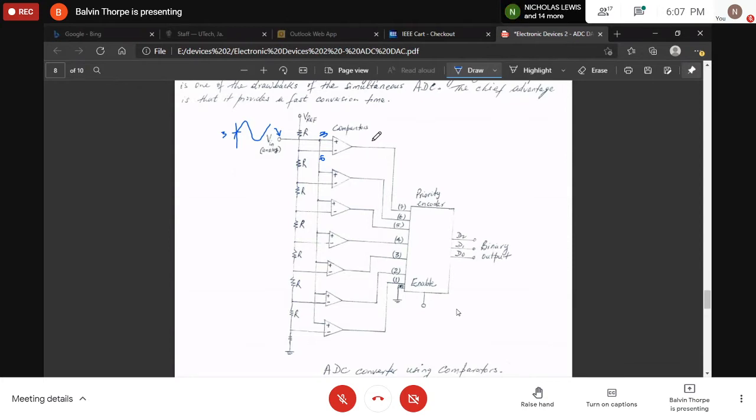Yes, so it's going to amplify a negative. Yeah, it's going to be driven. The amplification is what's caused it to be driven into negative saturation. So it tells you right away, because it has been driven to negative saturation, that the reference voltage is greater than the input voltage.